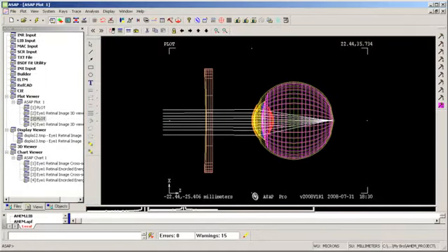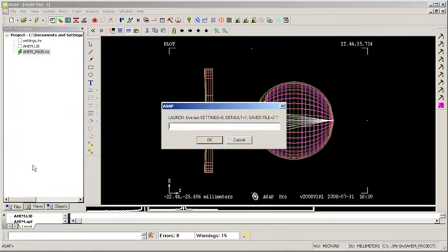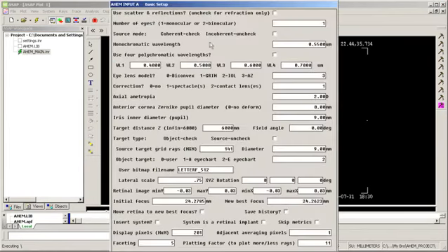So the ASAP optimization finished processing, and it gave me a number for the sphere. Right now we're looking at a graphic of the ray trace after I've put sphere on a corrected lens. So let's see how that looks when we run it. Alright, so I've got my eye set up basically the way it was before, where I had two diopters of ametropia on it, and I was getting that axial myopia where the rays were focusing before the retina.